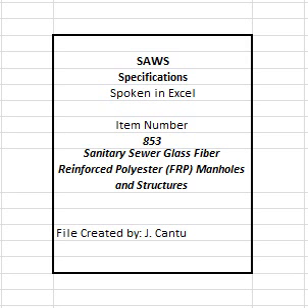Any existing manhole/structure which fails to pass the vacuum test shall be closely examined by the inspector and the contractor to determine if the manhole can be repaired. 1. Contractor shall either repair or remove and replace the manhole as directed. 2. The manhole shall then be retested as stated above. 3. The owner may elect to simply remove and replace the existing manhole with a new one at no additional cost to the owner.